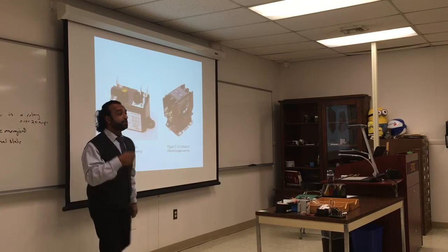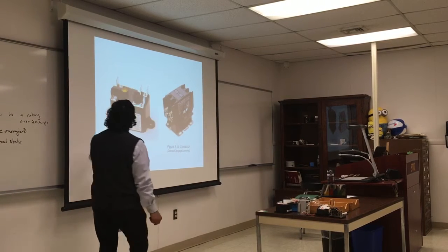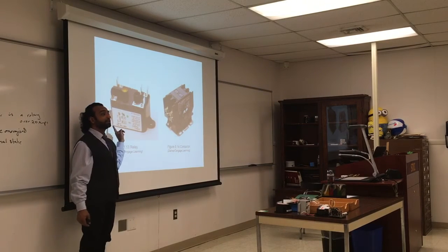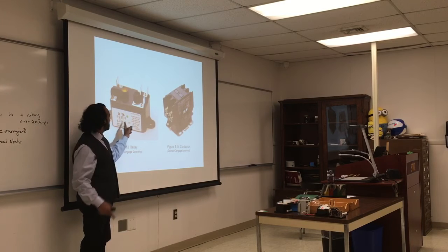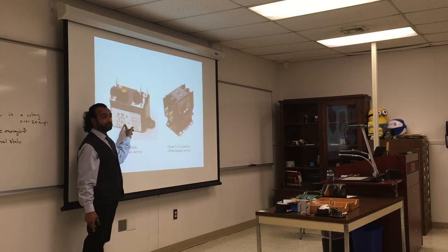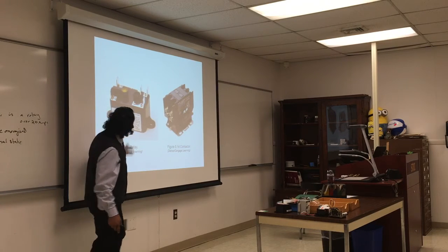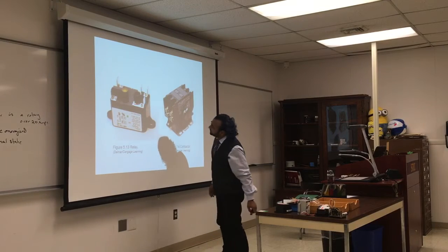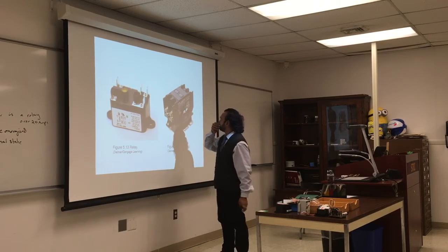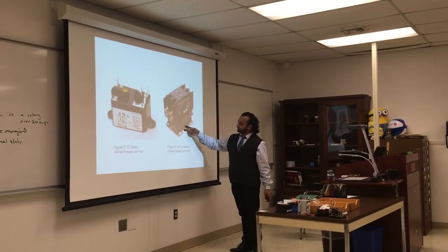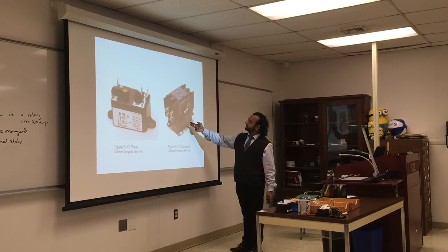So when they put the contacts on the sticker, they put it in this normal state when it's de-energized. Is this normally closed or open? Open. And they have the number for those terminals. This is a relay. I don't see the amperage. That's a relay. That's a contactor, over 20 amps.